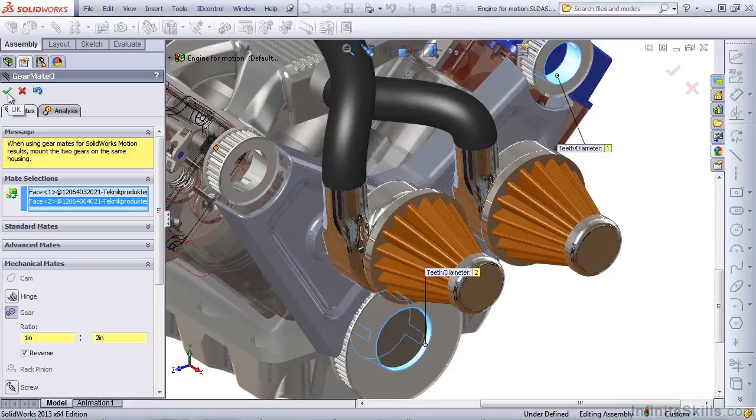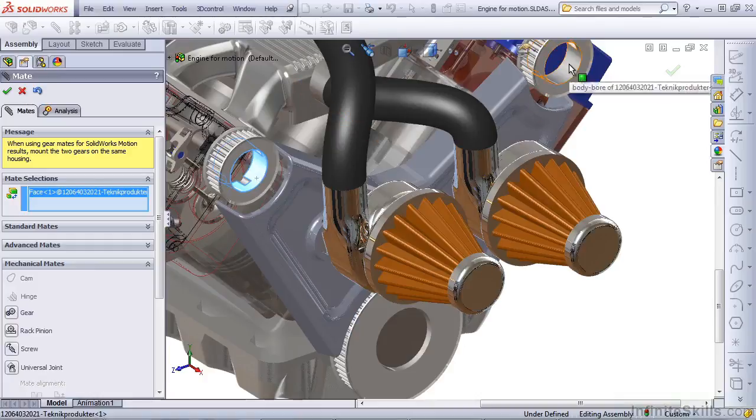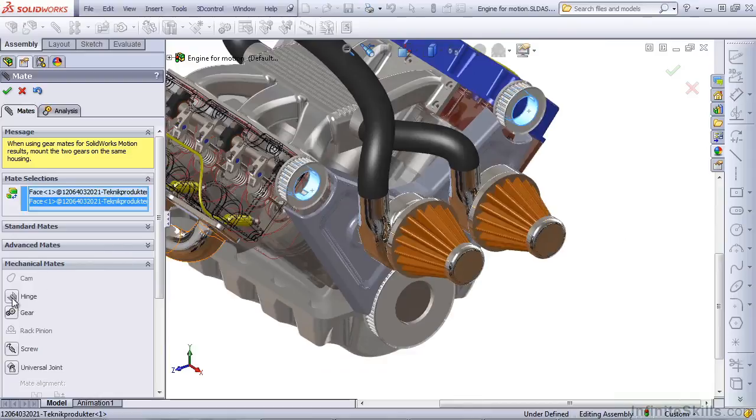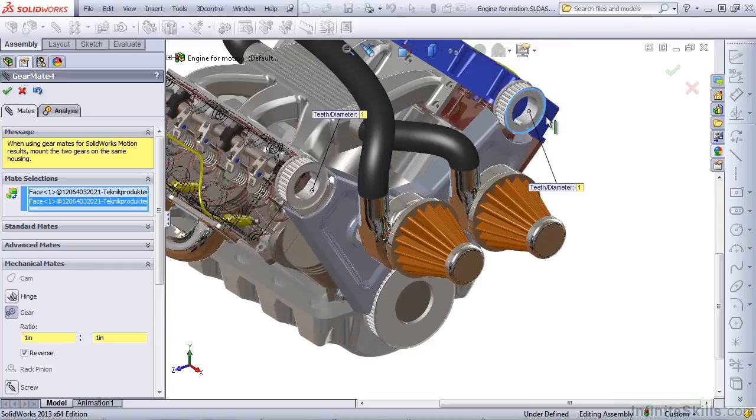Now we need to create the motion for the second one. For the second small pulley, really it's easiest if we just select the two small pulleys and give them a 1:1 ratio. Okay, and we should be good there. Now again, let's test direction, and the direction is correct. You can imagine that belt going around.